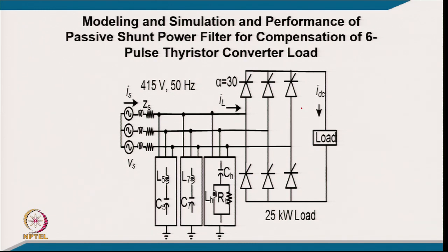You will find this typically in a DC motor drive, I mean a thyristor converter with firing angle control. Or you might have a magnet power supply, or a field excited synchronous motor, or typically large alternator field excitation, or even the converter used to derive a current source for the current source inverter.